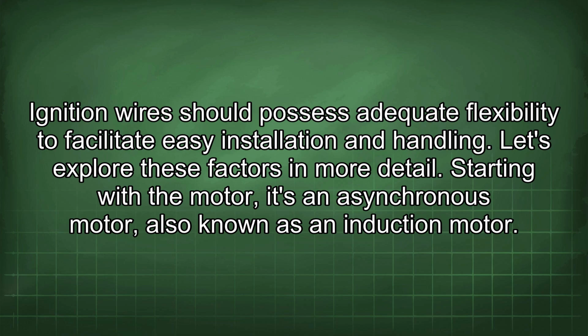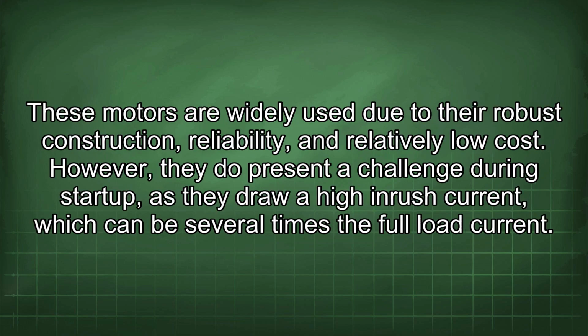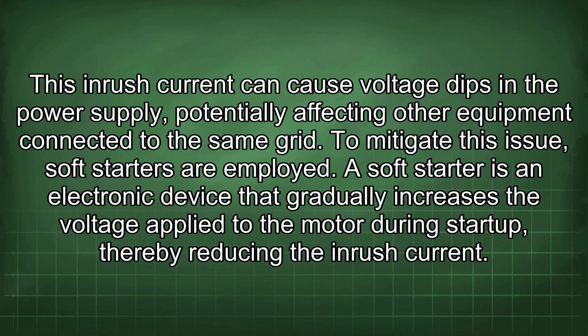Starting with the motor, it's an asynchronous motor, also known as an induction motor. These motors are widely used due to their robust construction, reliability, and relatively low cost. However, they do present a challenge during startup, as they draw a high inrush current, which can be several times the full load current. This inrush current can cause voltage dips in the power supply, potentially affecting other equipment connected to the same grid. To mitigate this issue, soft starters are employed.